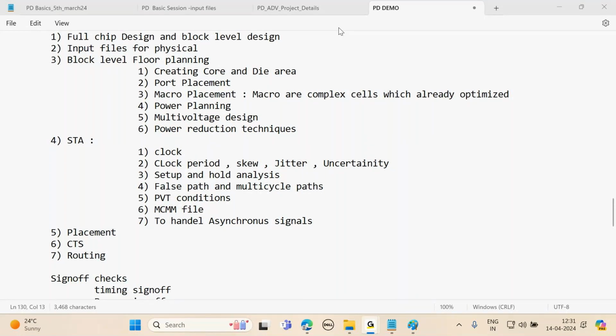But here you're using the Synopsys tool. You're doing hands-on with ICC2 or Fusion Compiler. Currently we have ICC2. If we go for renewal, we may get the higher version called Fusion Compiler. Both are the same; the commands are the same. Fusion Compiler has some advanced features: we can invoke more licenses. A separate license is not required for synthesis or for timing sign-off. All licenses come under one bundle, called Fusion Compiler. The usage and methodology of Fusion Compiler and ICC2 are the same. Only licensing is different, and you are nowhere involved in that; the licensing team is involved.